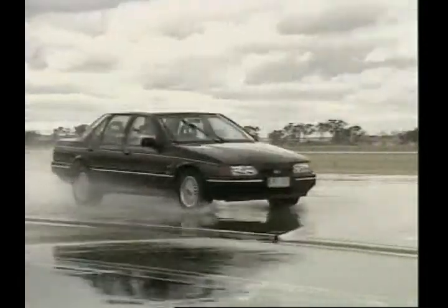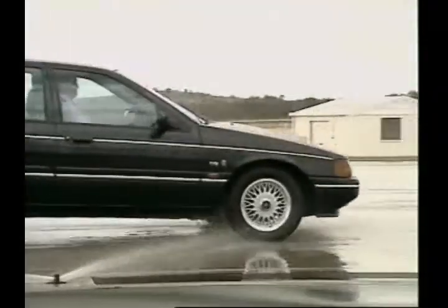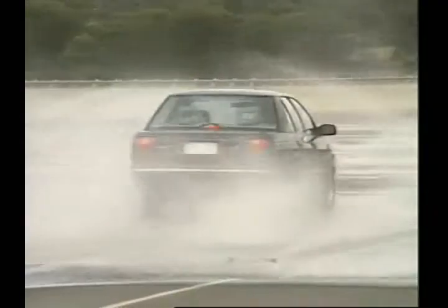In wet conditions, the coefficient of friction between a smooth tyre and the road surface falls to an extremely low value. Grooves in the tread pattern clear water away from the contact patch area. This allows a relatively dry area to be formed and for road adhesion to be maintained.